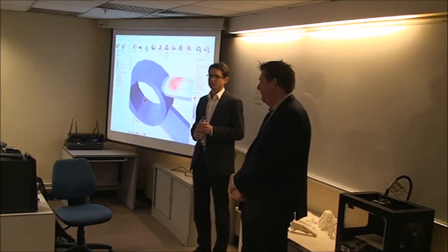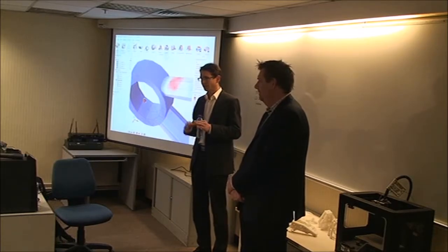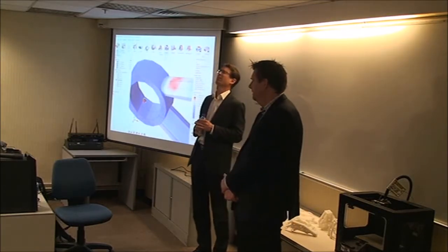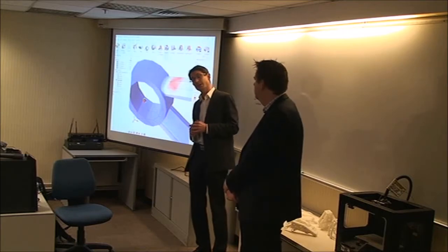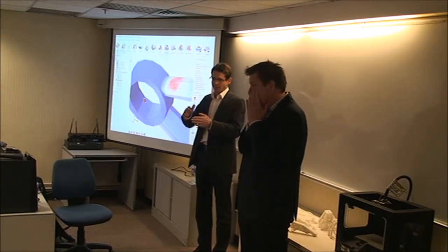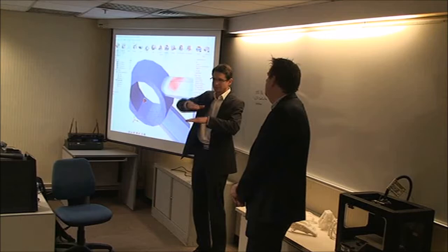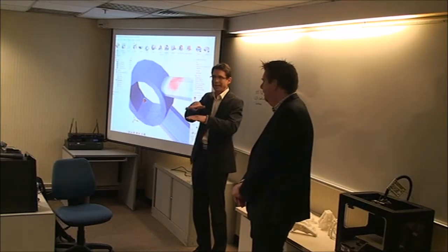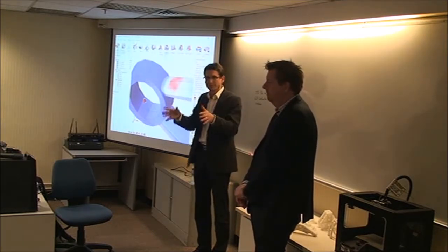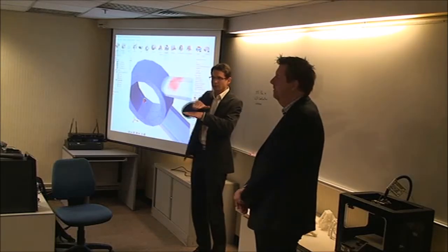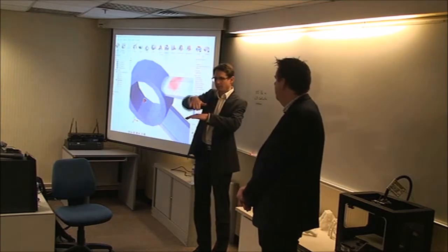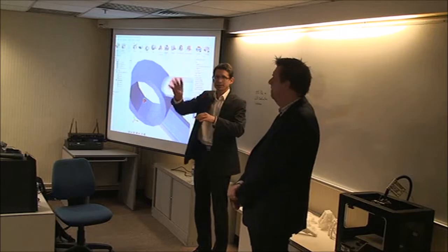I would not say it's 3D printing, it's 3D patch layered ring. Three years back, I had a bike saddle optimization where a manufacturing tool maker had a process to place small patches of different angles by a robot, and we helped them optimize a carbon saddle: what patch, in what direction, with how many layers, and so on. That was our job, to optimize that, and then the machine puts them one after the other, and then the resin comes and it's done.